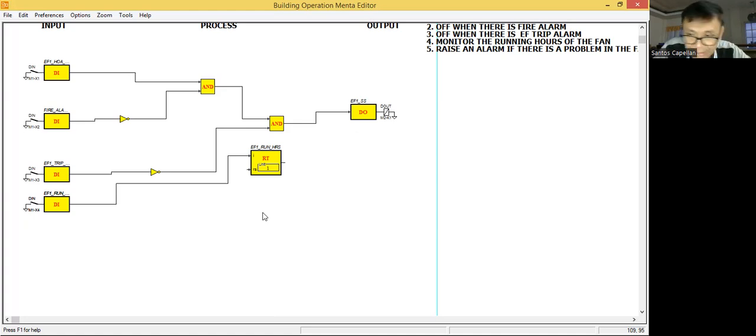Then after doing the maintenance, the maintenance people will notify the operator. Then you can reset the run hours. Now actually these alarms should be logged. There should be some history. When I was in maintenance, we were doing this maintenance job for this equipment, and it will be checked from time to time: when did you perform the preventive maintenance for this equipment?